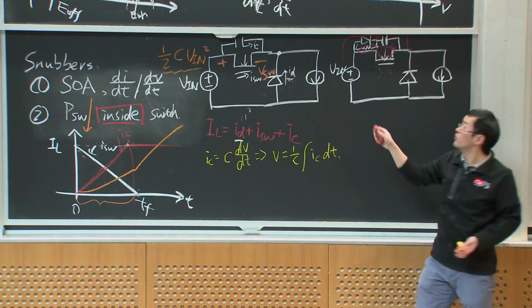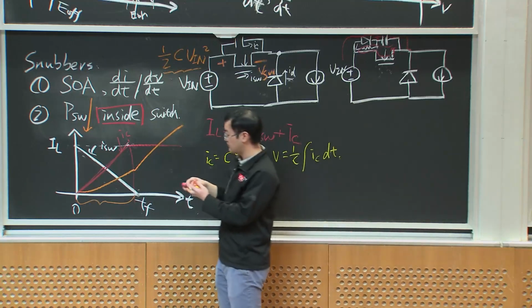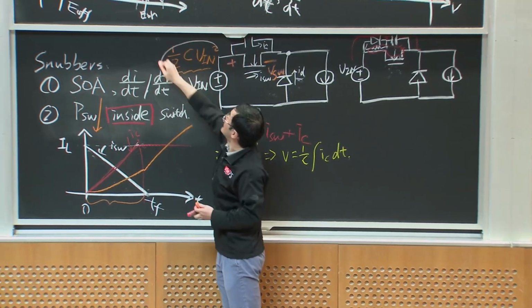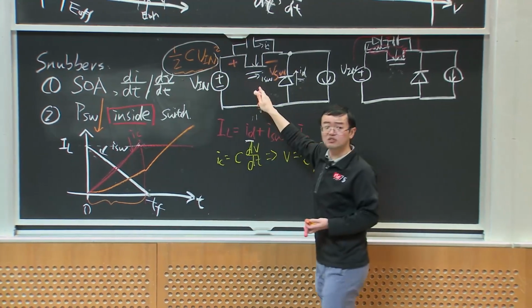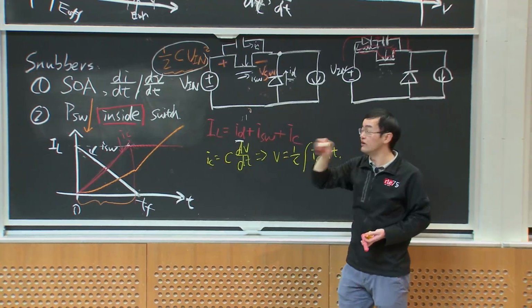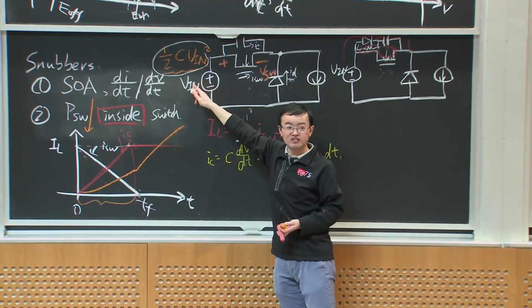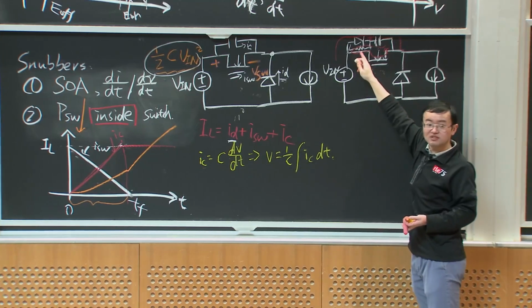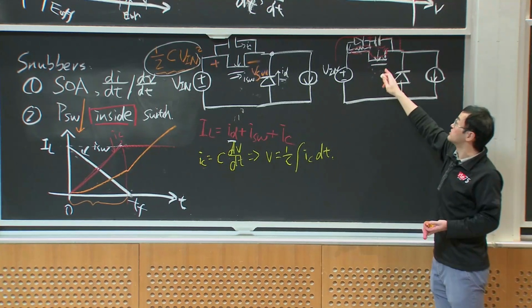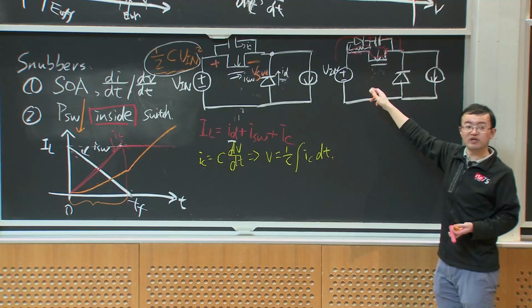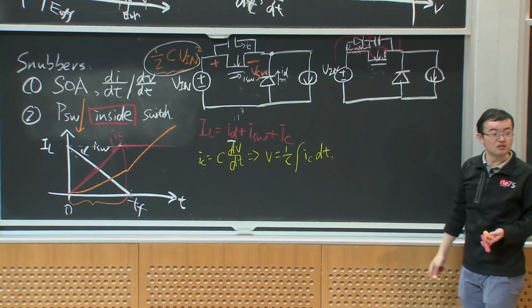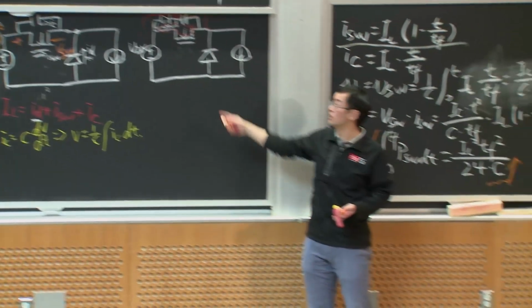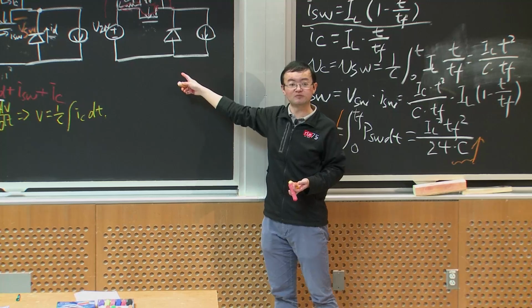And in this way, we solve this part of energy that could destroy our device during the turn on. But again, we do not recover this part of energy. This part of energy is still dissipated, mostly on this resistor and a small amount in this MOSFET. But we can improve this. So do you have any questions for a practical turn-off snubber?